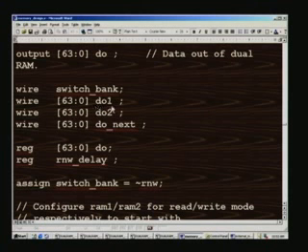That is why we have nomenclature as DO1 and DO2, and DO next, as we have used earlier, is to indicate the next value of DO, which is the register value that will be at the next positive clock edge after this DO next goes active, and DO is the output. We had to declare all this as wire because they are all assigned statements, and this is basically in an always block with a positive edge clock,